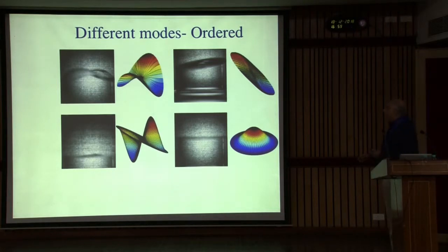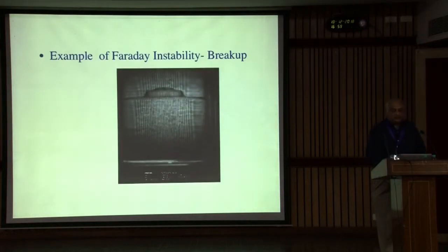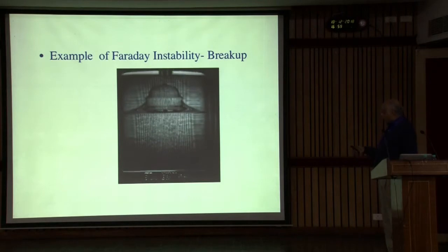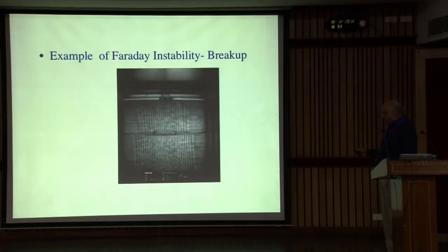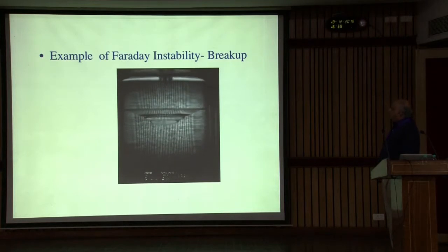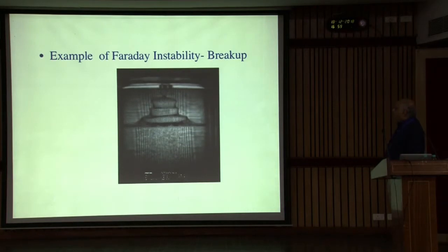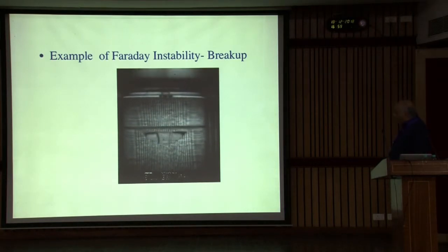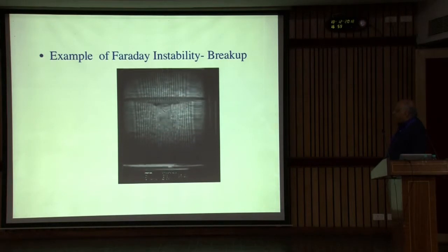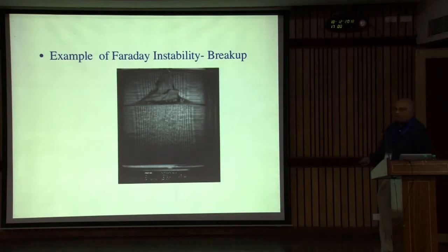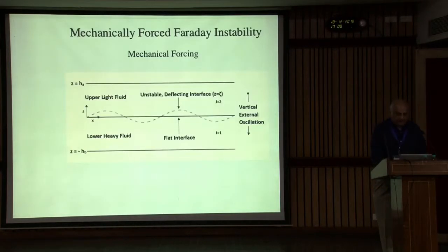But the other thing that I want to point out is that the fluid state that you have here saturates to a nice pattern. That's not always true. You can run a system such that the mode that you get does not quite saturate, and in fact it will break up sort of catastrophically. And so if we look at this for a few seconds, you are about to see the lower fluid, which is heavier, not just invade the upper fluid, but now actually break through the interface. So you're going to see what we will term later on as a subcritical instability.